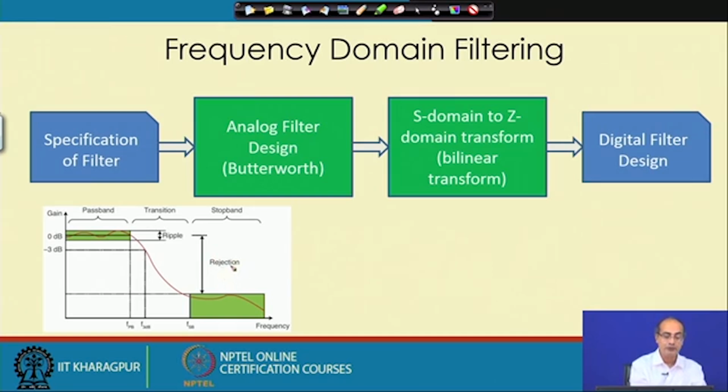Next, some people would like it to be close to the ideal filter, that means there should not be any change or undulation in the pass band. So, they try to control how much ripple there would be. These undulations are called the ripple, and we specify the maximum allowed ripple.